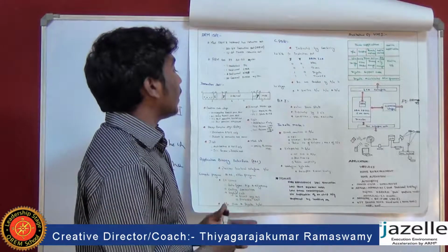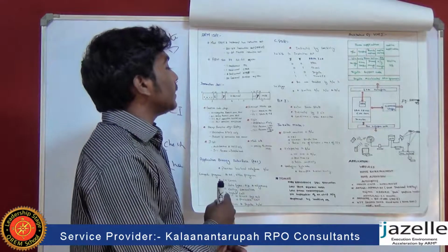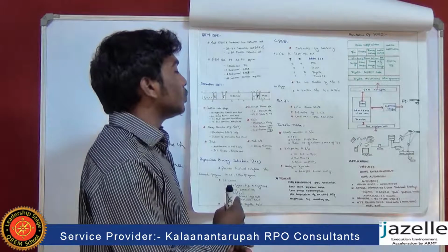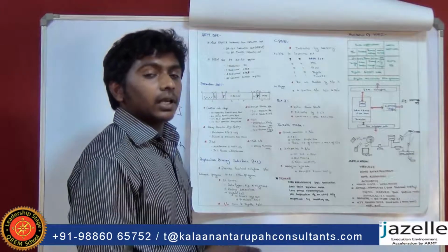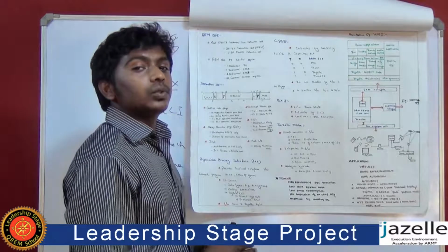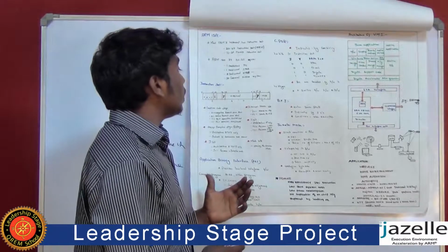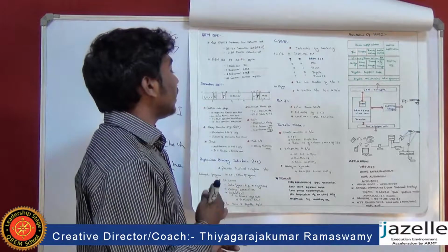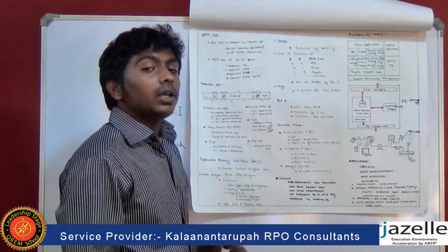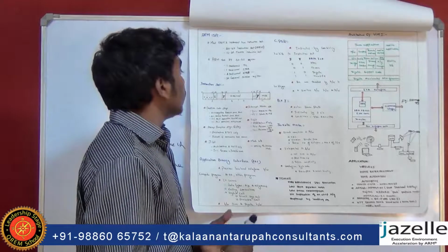And the next bits are the interrupt disable bits. The first bit is an I bit, that is used to disable the interrupt request, and the second bit is an F bit, that is used to disable the fast interrupt. And the next bits, from 8 to 23, are undefined bits. Those bits can be used in future for some other purpose.